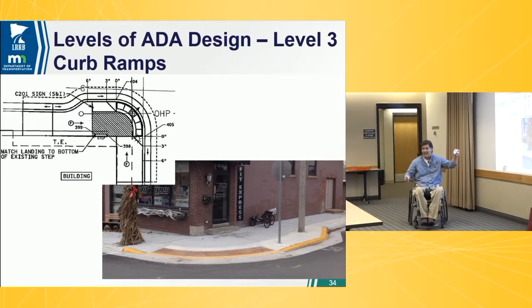You've got to tie in from curb to tie-in. Those other ones we talked about, that was that S slope or F slope. Contractor can just round up 10 feet in those areas. It's not the end of the world. We should get our quantities right, but they'll still figure it out. This, you're tied in everywhere. So you've got to get it right. There's no rounding up another panel here. You're just going to miss if the elevations are off.